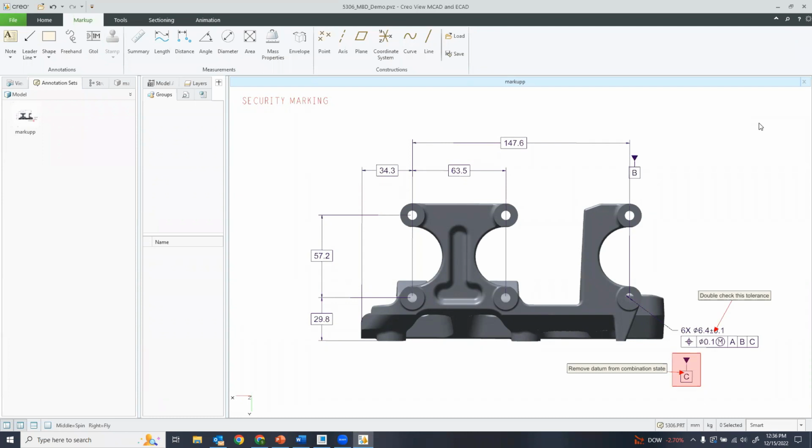And I think the thing is when you're using a 2D print and you're not verifying that your model is set up correctly, sometimes you may fake an annotation on the 2D print and your geometry doesn't accurately represent that. So obviously step files are fine. And I think MBD just helps you verify that your geometry is correct, because I'm not sure if step can do flat to screen annotations.